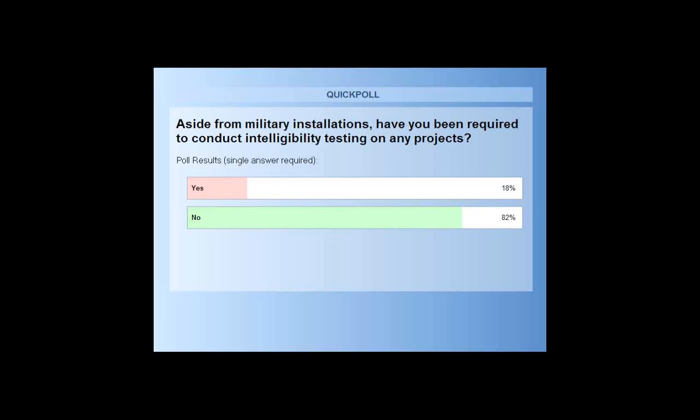I haven't talked about it yet, but that software allows you to input all of those variables at the beginning of your project so you can take into account different structures in a building and different materials on the wall and the floor, and that will let you know where you should install your speakers and what they should be tapped at in order to meet a specific intelligibility score. If you're not using any particular design software, it's very hard to tell exactly what is having the effect on intelligibility. Our recommendation, as I mentioned earlier, is that more speakers at lower tap settings are what is going to help you meet the scores that you're looking to meet.